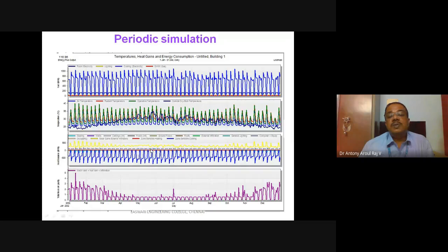You can see these small things and decide how much the load will be. Here these are all the cooling loads. The pattern is the same, except whenever the load is higher, where we have different patterns. Something interesting here also is that because of exposure during January, February and December we have higher loads. How can you correct this? You can change the orientation of the glass, so that you can correct this.